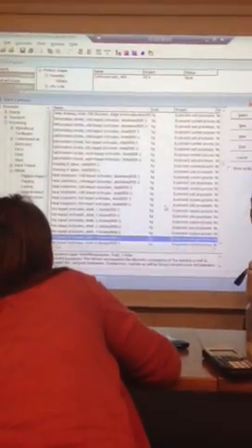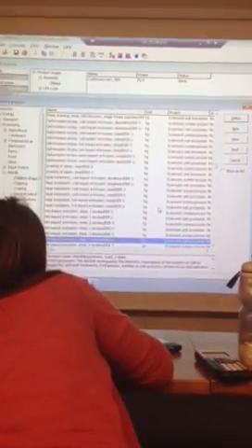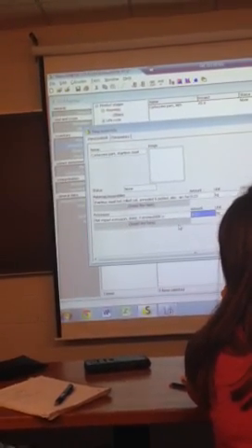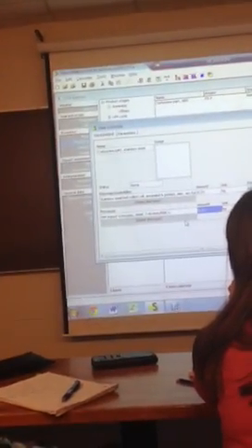And if you have any questions, let me know. Stop me. It specifies that it's 3 strokes, and you always want to select the unit process that has the U at the end, and not the system process. And this one will basically have a lot more detail when you look in the network and see all the sub-processes that are included in it. So select that. Again, we specify the amount, which is still going to be 123 kilograms. And then we just do the same thing for the next 2 processes.